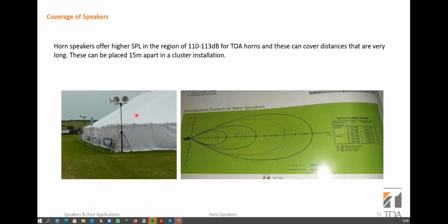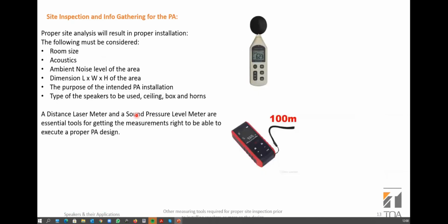This is the reason why, ladies and gents, if there are any ladies, we don't recommend that you put horn speakers inside the office place. You'll be asking for trouble. And number two, though you can put horn speakers in a manufacturing plant, we do recommend that. Or if you are doing outside broadcast, we also do recommend that. Or if you are dealing with a mall, a hospital, or a building that has a basement where they park cars, you can also put horn speakers in there. Always try and avoid having horn speakers anywhere else.